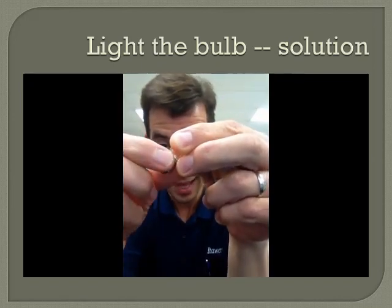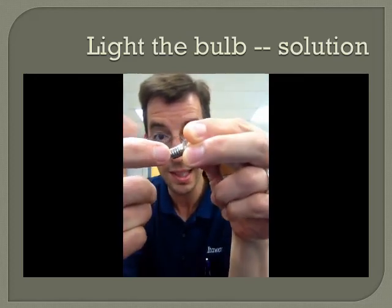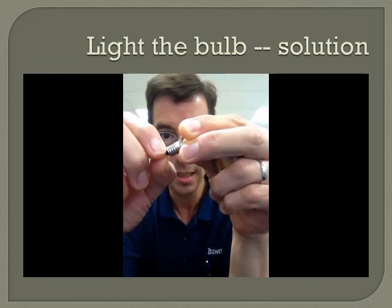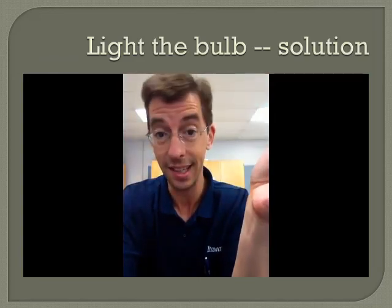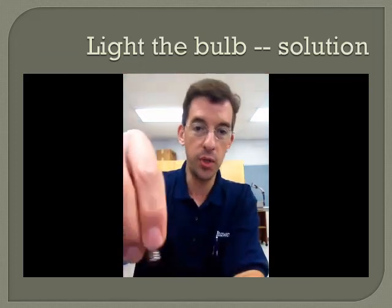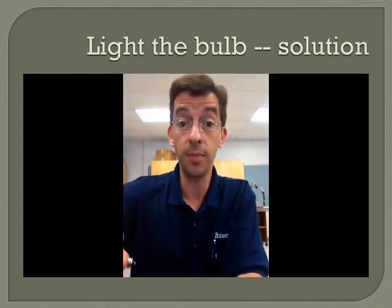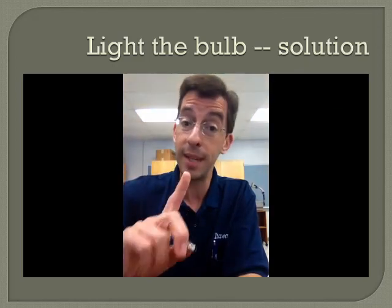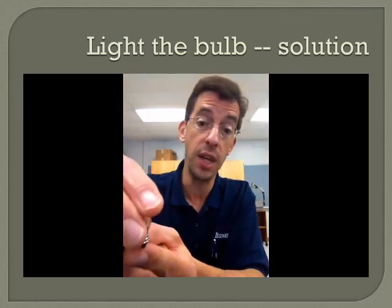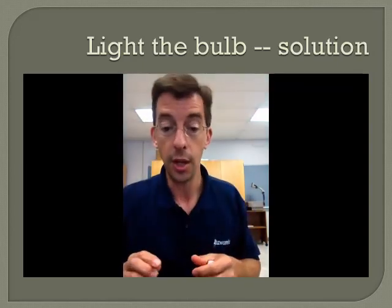Notice that the housing is made of metal, the nub is made of metal, but in between there's an insulating material. It's a type of glass in between the two so that they are not connected electrically. That's very important because it turns out that even though we're used to seeing a light bulb screwed into a socket where it looks like there's only one connection, by screwing it into a socket you're actually making two connections. You're connecting to the nub and you're connecting to the housing. And that's what we want to do in order to light our light bulb.